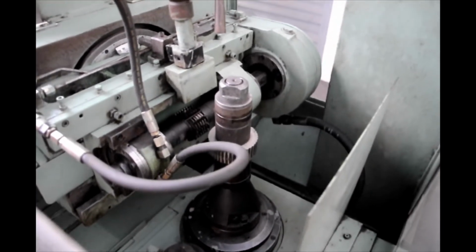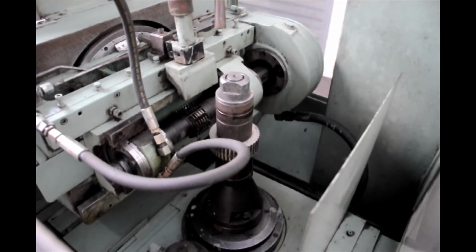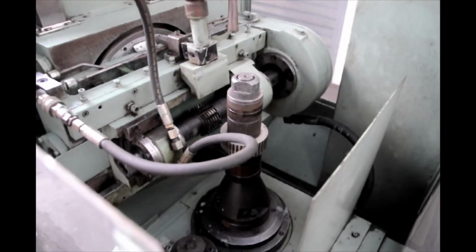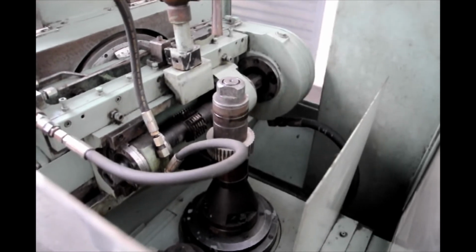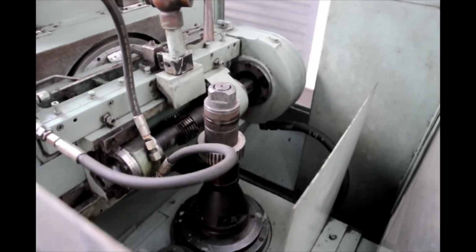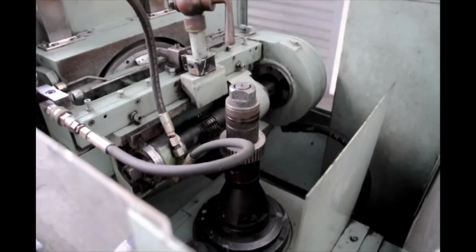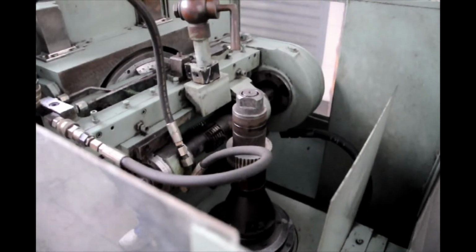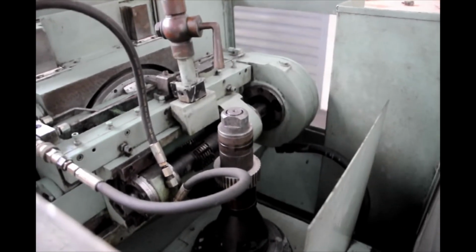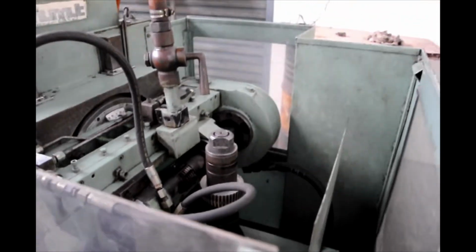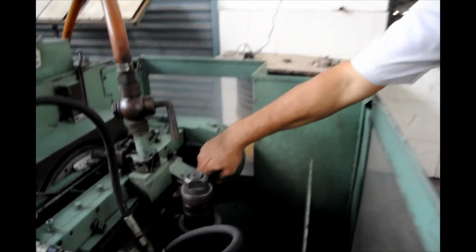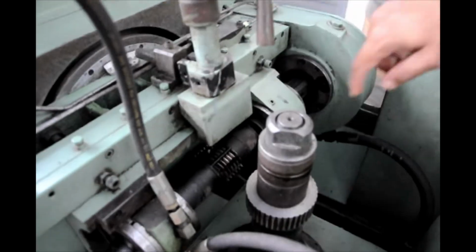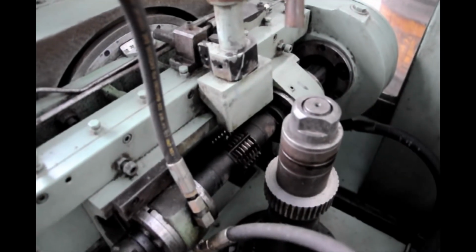This is also a machine made by Hindustan Machine Tools, Bangalore, and it is responsible for the rolling action of those cutters against the workpiece, and on the basis of that the typical profiles with the rolling action can be generated. It is also a production machine. If anyone possesses these kinds of machines with a limited range of modules, one can produce and supply to the automobile and other ancillary industries. A typical hob has starts, because it is cut, so that entry and other things are there.